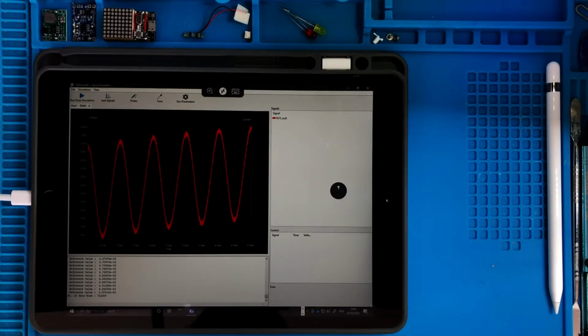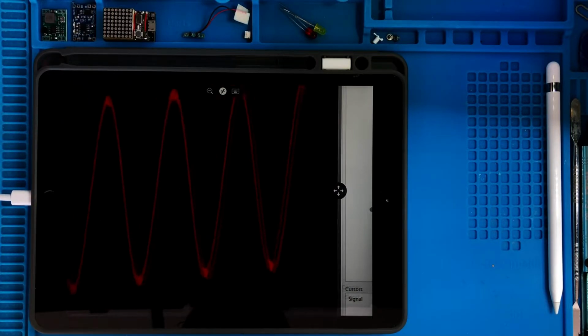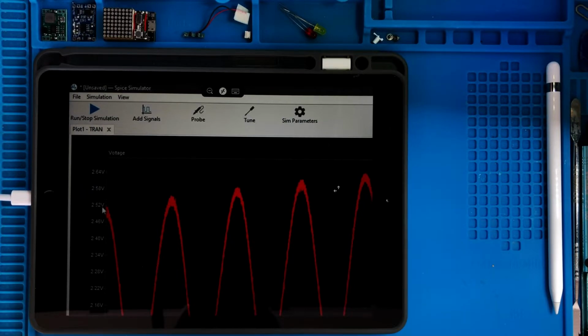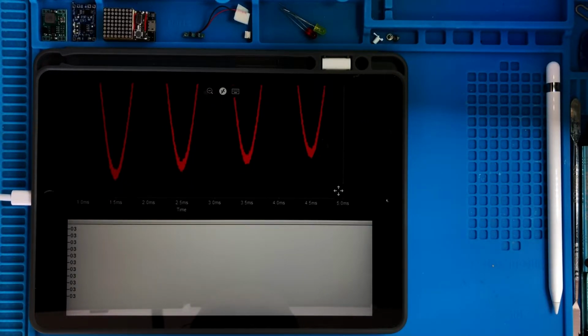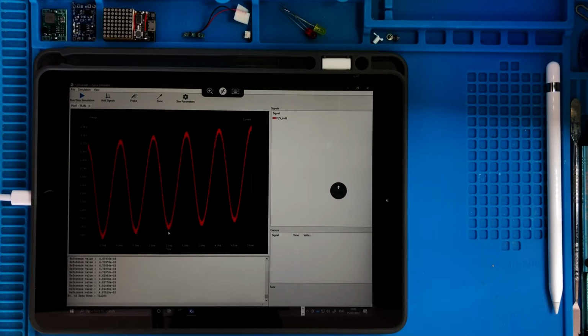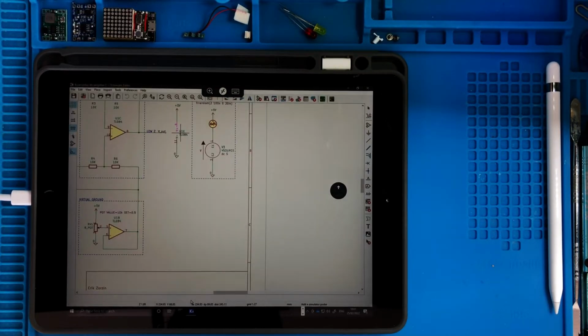So let's try to understand it. Maybe like this, it's too big. Here we have one axis, the axis of voltages. Then on the horizontal axis we have time. And we have our signal. You see that the signal is not perfectly smooth because there are noise sources in our circuits. Then, just to roughly understand what we did, let's take a rough measure peak to peak from this output sinusoid. It goes from 1.86 volts to 2.52 volts. So let's say it's about 1 volt of amplitude, a little bit less. So let's go to the schematic diagram.